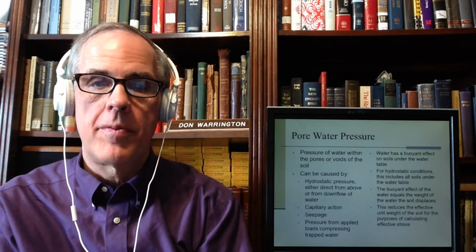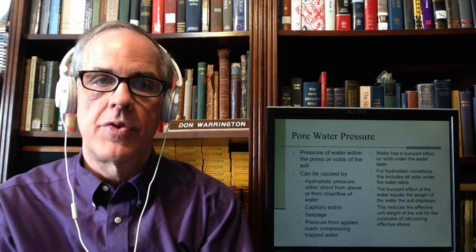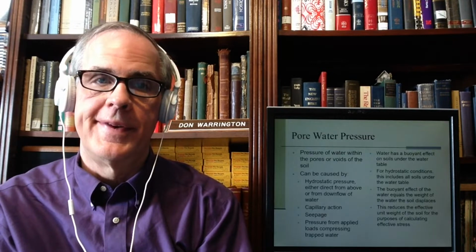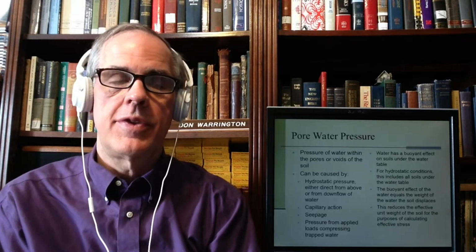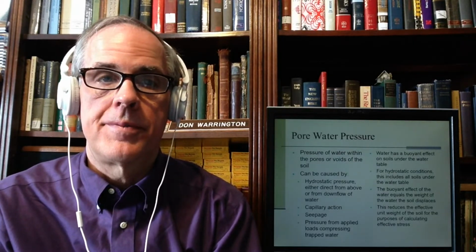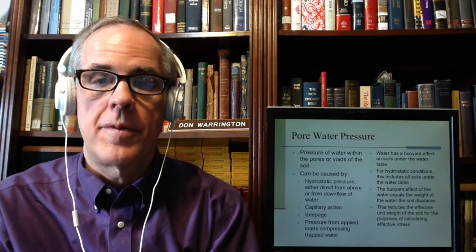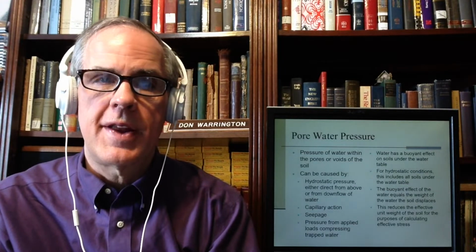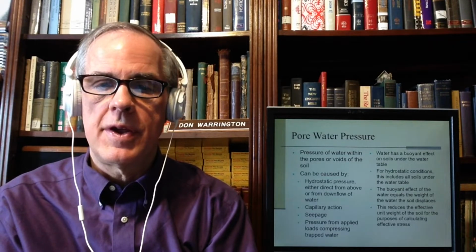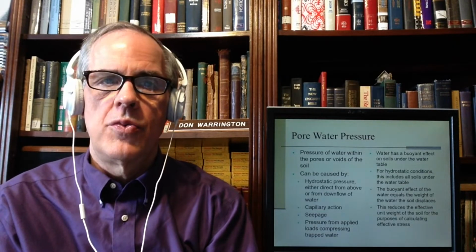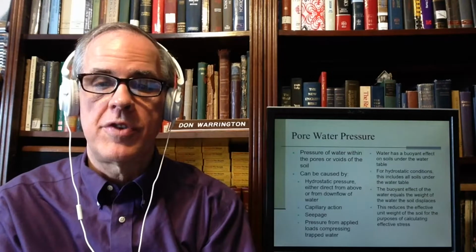Now let's talk about pore water pressure. As I said before, the pore water pressure should increase with depth under normal conditions. But we need to define what pore water pressure is. Pore water pressure is the pressure of the water within the pores or voids of the soil. It can be caused by hydrostatic pressure, and that's pretty much what we're going to stick with just for the moment. The rest of them, capillary action, seepage, and other things, we'll deal with most of those later. Capillary action, we're going to deal with very soon. Seepage is going to take a little longer.